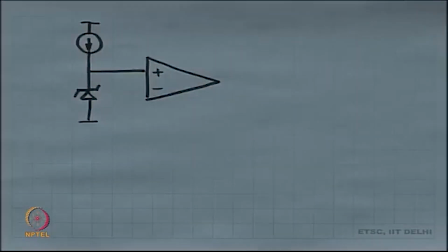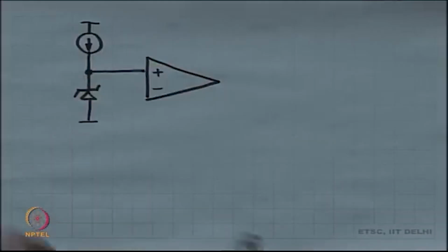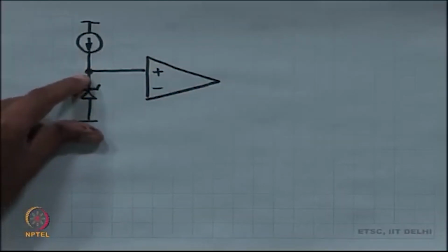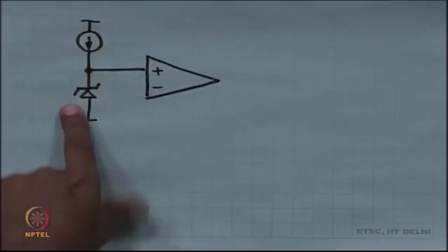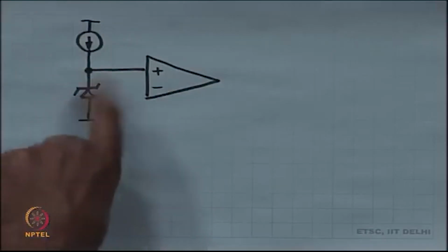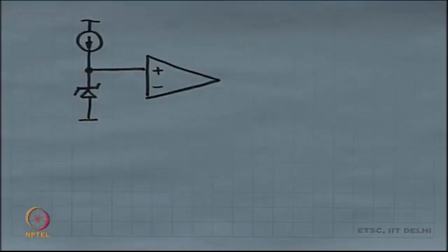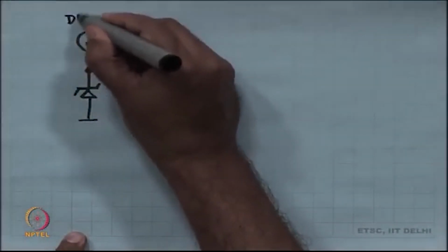This is the idea. All right, a lot of people use this Zener diode. So, I take this Zener diode and create a constant voltage. I push a current through a Zener diode, I bleed a current through a reverse biased Zener diode and create a constant voltage. And now, this is from the dirty supply.